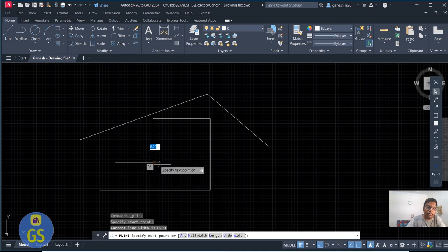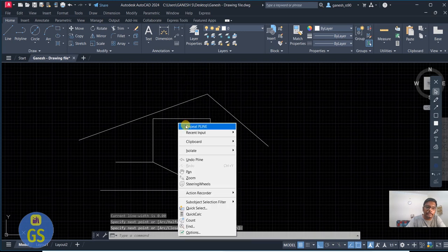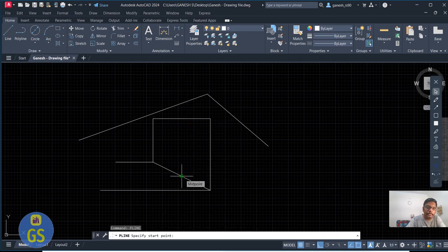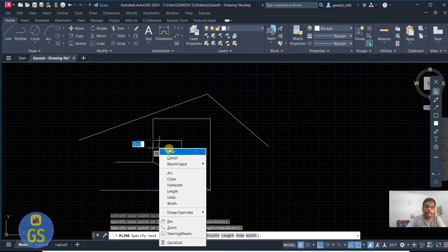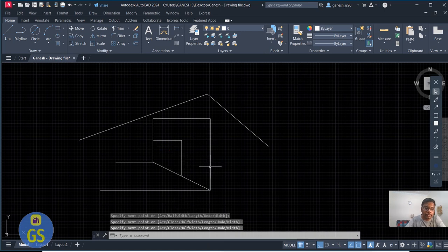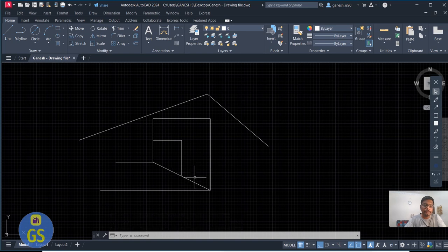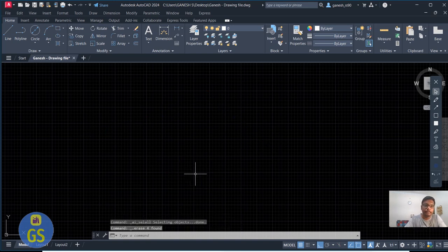You can select this point and draw a line to the nearest point, or find a midpoint in this line. Now I want to find the midpoint of this line, so you can see this and do like this. This way we make a sketch by using the object snap settings. That is the useful thing which you want to use.